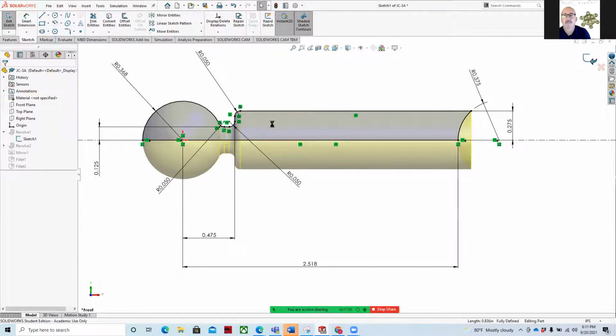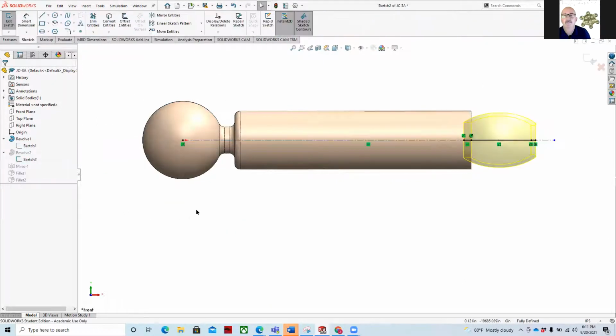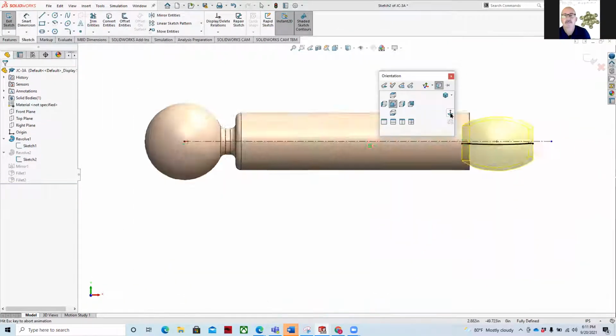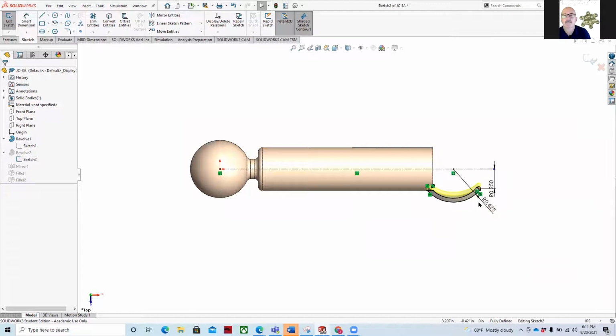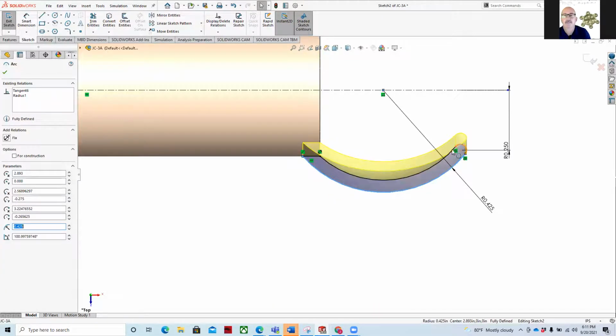Finish the sketch. So we create this sketch, and then after we have that sketch, we revolve it, and then we create a secondary sketch. If we look at the secondary sketch, and I like to hit the space bar, Normal To, we can see the geometry here. It really wasn't super specific as far as this end radius on here, so I don't think it's critical to the design piece. As we go in and start to work with this, we could make any changes we needed to it. But ideally, if we were to go back here and take a look at